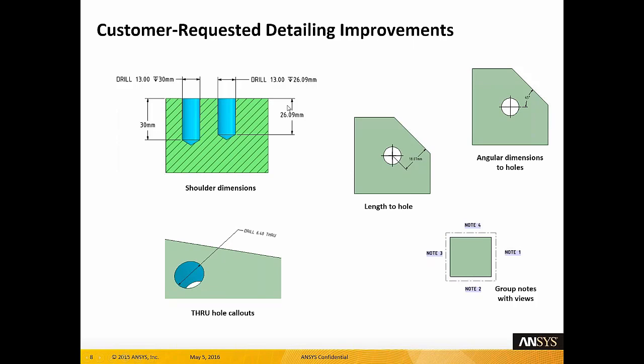In this case, if you do the depth dimension, it now will only go to the shoulder if you have a point at the end of the standard hole. This is a nice small improvement. It's really a more appropriate way to dimension these.